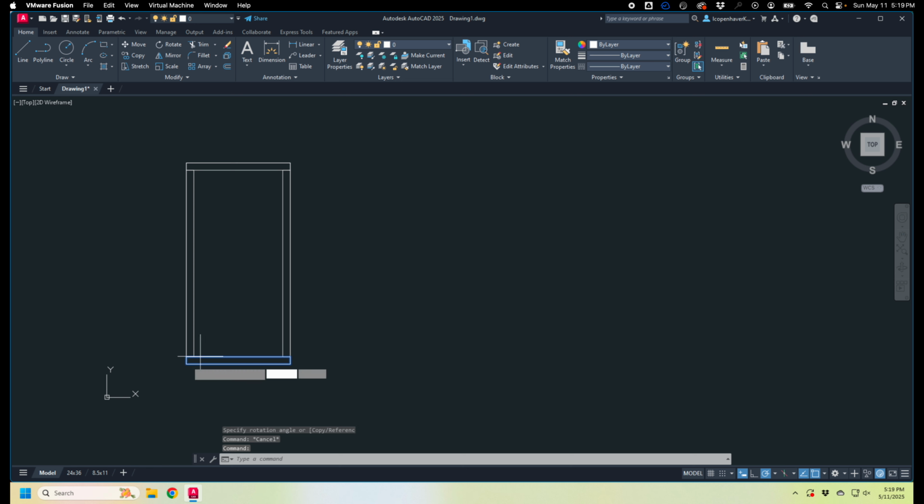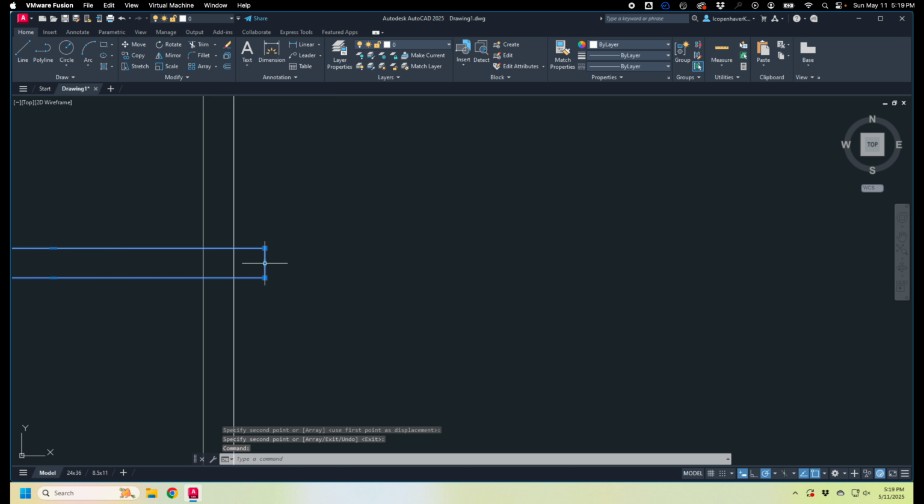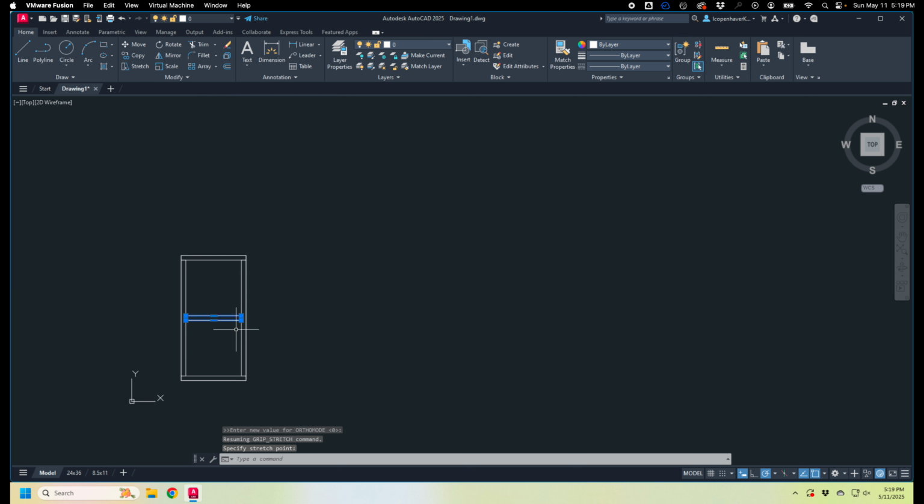Let's copy this, place it in the middle like that. And then we're just going to use some of that functionality that I said we seldom use, and that is the stretch functionality. So I'm going to click this. I'm going to hold shift to force it to snap to its 90 degrees, and then go to there. So that's given me a rectangle.